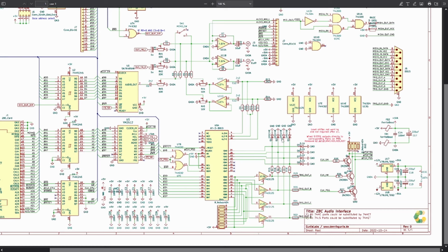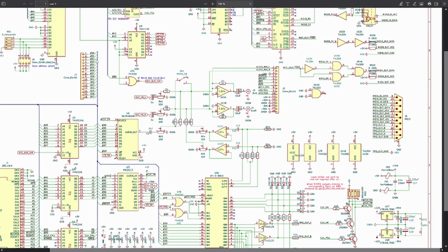And that is basically it. That's the entire PCB. The only thing that I didn't mention is these two connectors, which I also won't populate for now. These basically allow me to add additional sound ICs in the future if I want to, and not have to design a completely new board, only add a small board on top. I can plug it in on those two connectors, and then I can add an additional sound chip like a SID, for example, and still mix it into those two outputs. All right.